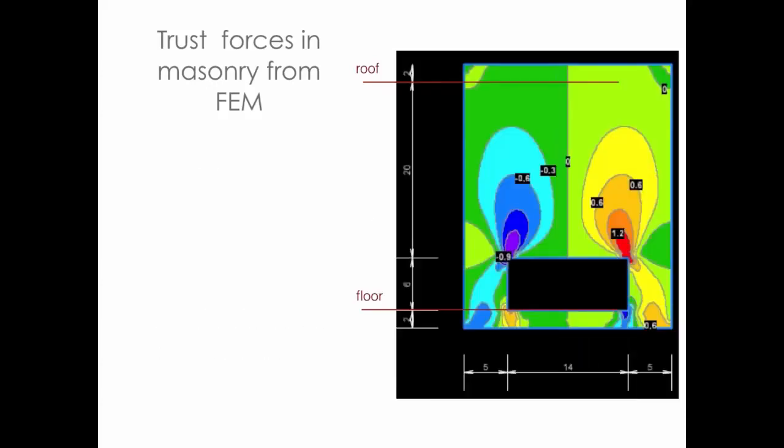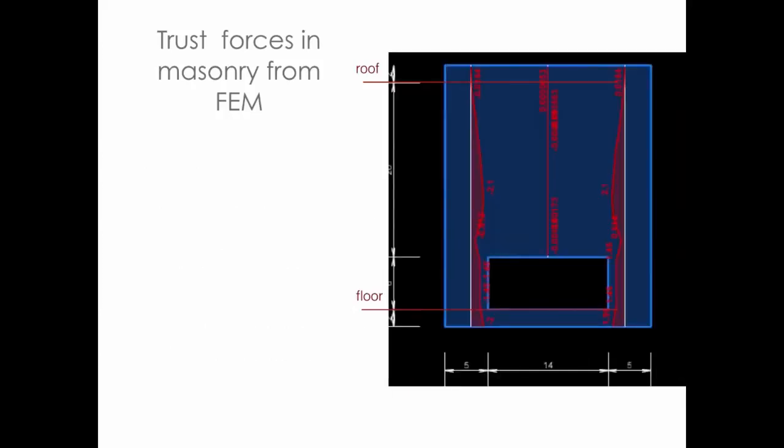right? And even for the longer opening, granted, my thrust loads are a little bit higher. You can see the colors are a little bit more intense. I can see that I have more forces there. But again, looking at the values, you can see that they do start collecting up within the wall. It doesn't, again, wait till it gets to the opening and then shoot out some forces. In fact, it kind of balances a couple feet above the opening, and then it stops, giving it a thrust force, which I think is kind of interesting.